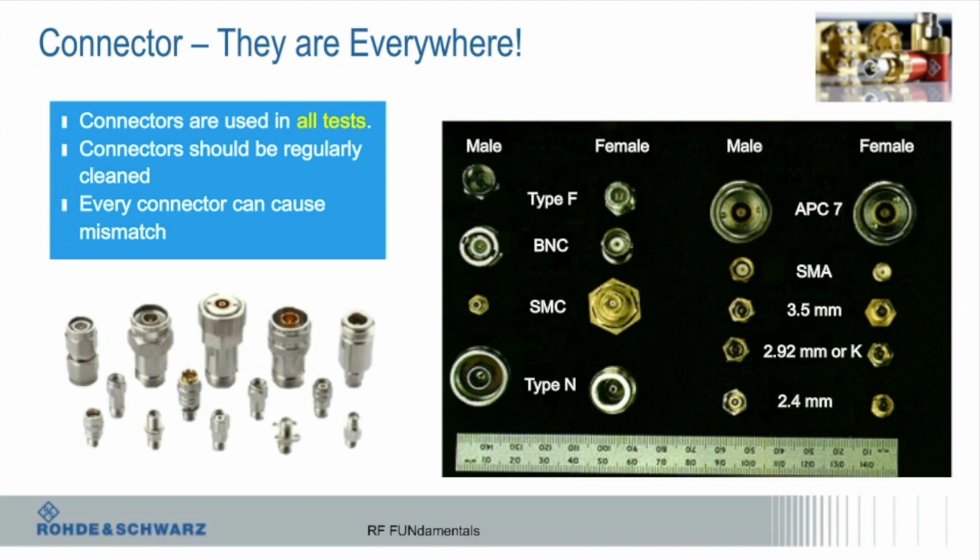I think I started saying this, but I had a guy, we had a 2.4 millimeter VNA, so 50 gigahertz, and a 3.5. A 3.5 and a 2.4 do not mate. If you try to screw them together, they won't mate. But apparently, if you try hard enough, you can make them mate. It's good for one insertion. The performance is really bad. We'll say it's not repeatable, so don't do that. But it's okay for us, because then we get to fix your thing and make you happy again.